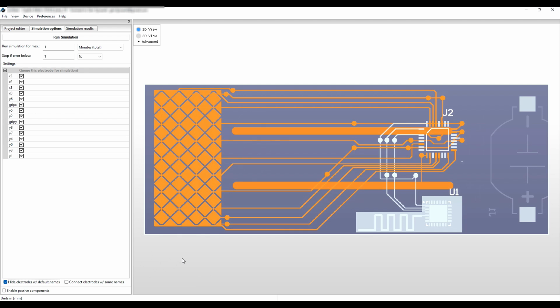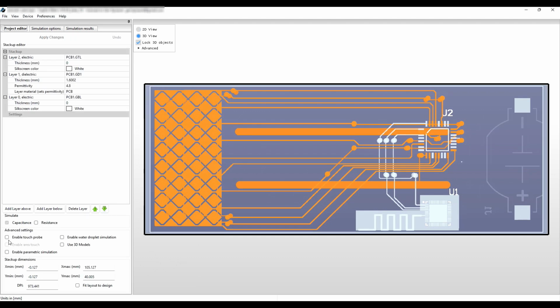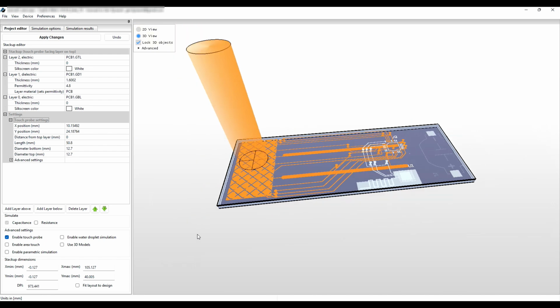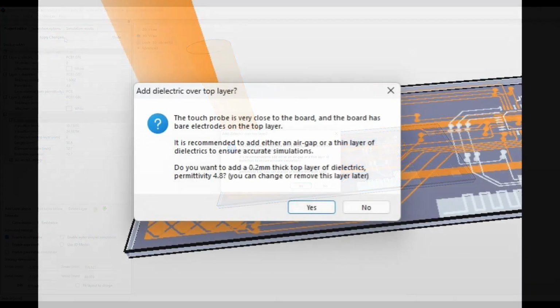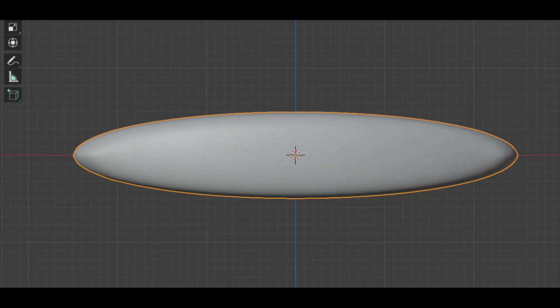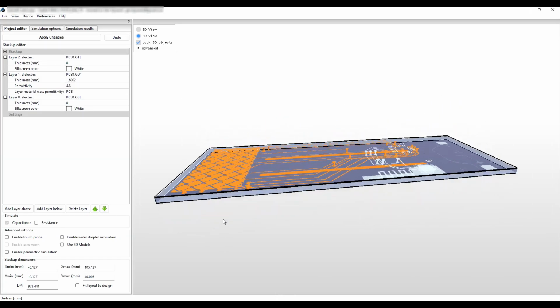Now, in order to evaluate the performance, we need to apply some dielectric layers over the electrodes. Otherwise, our results will not be useful for a first-order validation of the board. In general, capacitive touch requires a non-conductive overlay that separates the finger from the touch electrodes. The remote control has a maximum thickness of 10 millimeters, but this varies. We will add overlays of 3 millimeters thickness to both sides of the PCB. That should work well for a rough validation of the touch performance.